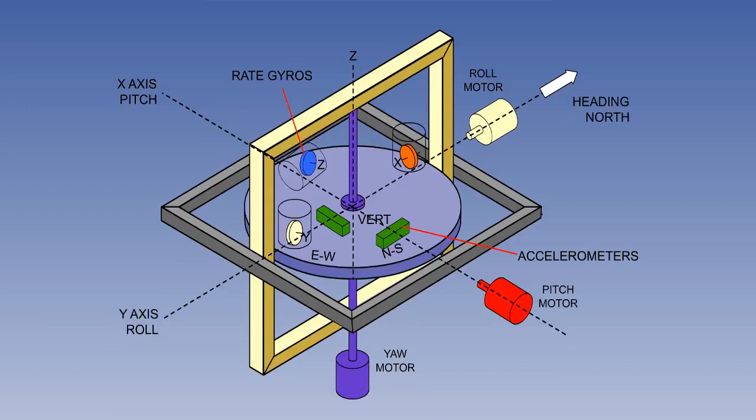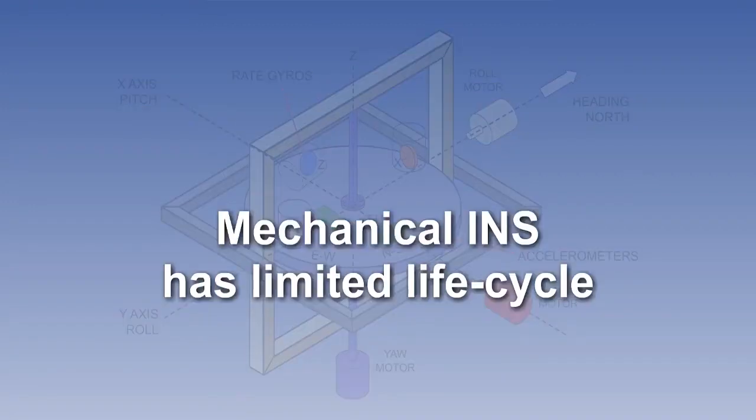For the INS to work, the response and correction to any sensed manoeuvre has to be near real time, and the accuracy has to be better than 1/10 of a degree in all three planes. Additionally, the platform, which contains 2 accelerometers and 3 gyros, is quite heavy. The design of the platform servos was a demanding engineering challenge. Because of their mechanical complexity, the early platform servos had a limited mean time between failures. This was one of their known weaknesses, and it is one that has been overcome in the later inertial reference system.